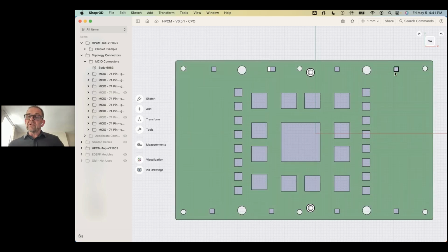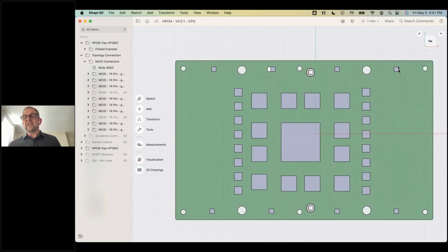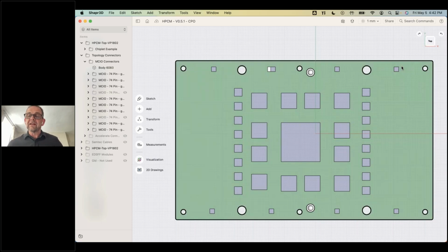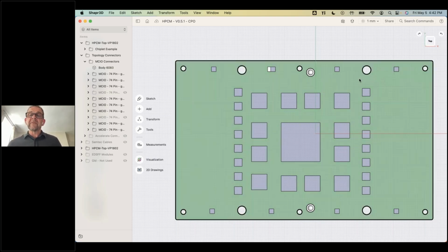So we were already talking about your little IO chiplet that's directly below the connector, and that's less than a dB, and then you've got another 29 dB for the cable itself. And the cable is very efficient compared to PCB routing, so you could probably get many meters of distance even on the thinnest gauge cable.